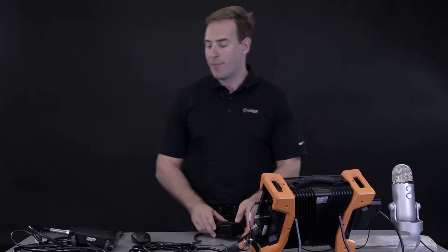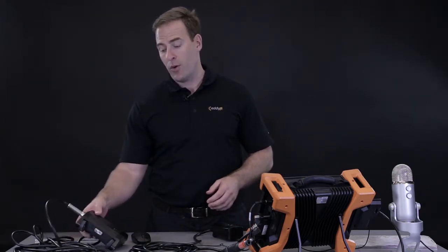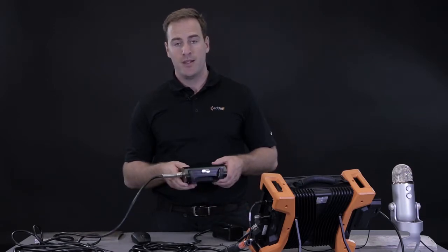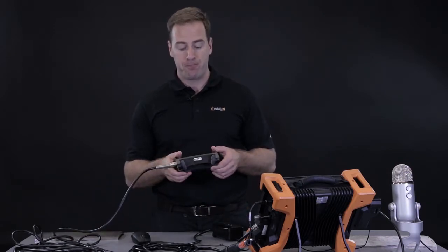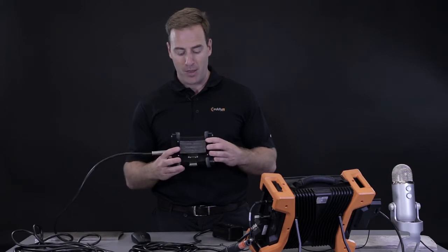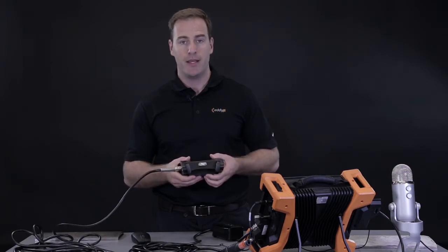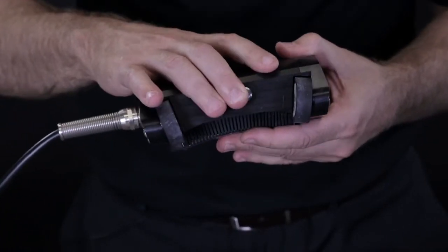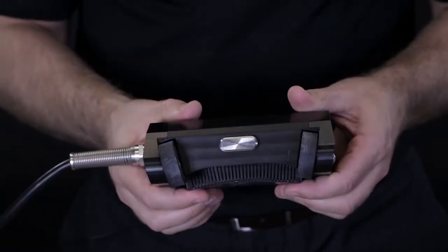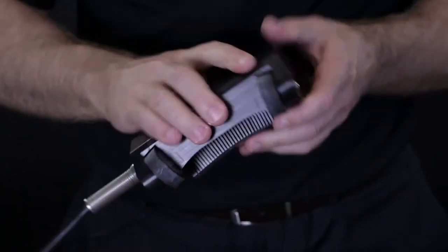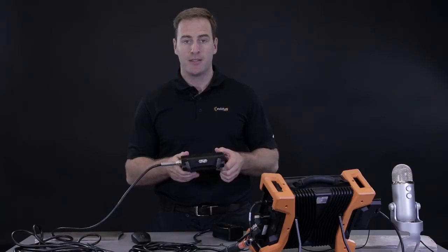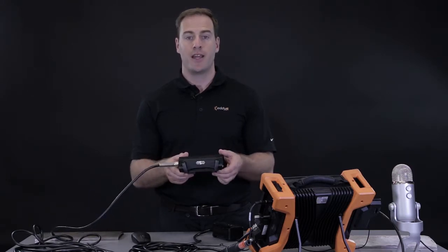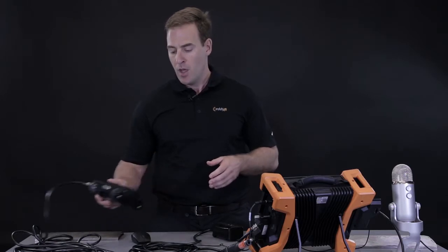And the other probe that I'm going to demo a little bit later will be the high-resolution version of this butt weld probe. But this mechanical design mainly helps to inspect the pipe surface, not the weld. So we have a flexible shoe here which can fit the pipe diameter to be inspected. And based on this design, this probe will carry only longitudinal scans along the pipe.